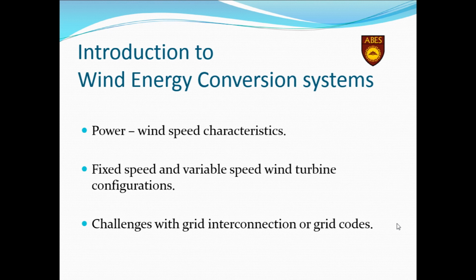The topic is Introduction to Wind Energy Conversion System. In this topic, there are three major areas which we have to focus. First area is power wind speed characteristic. Next is fixed speed and variable speed wind turbine. Third one is challenges with grid interconnection or grid codes.